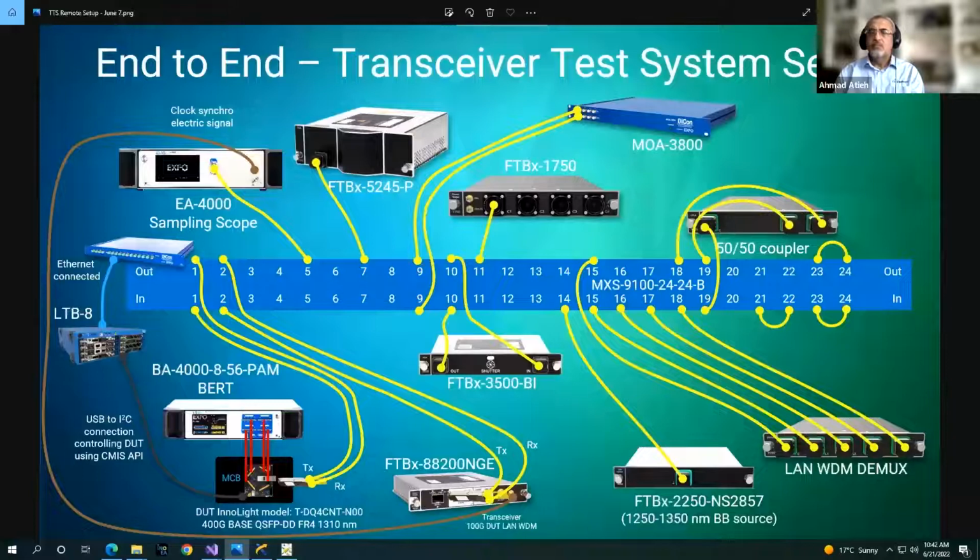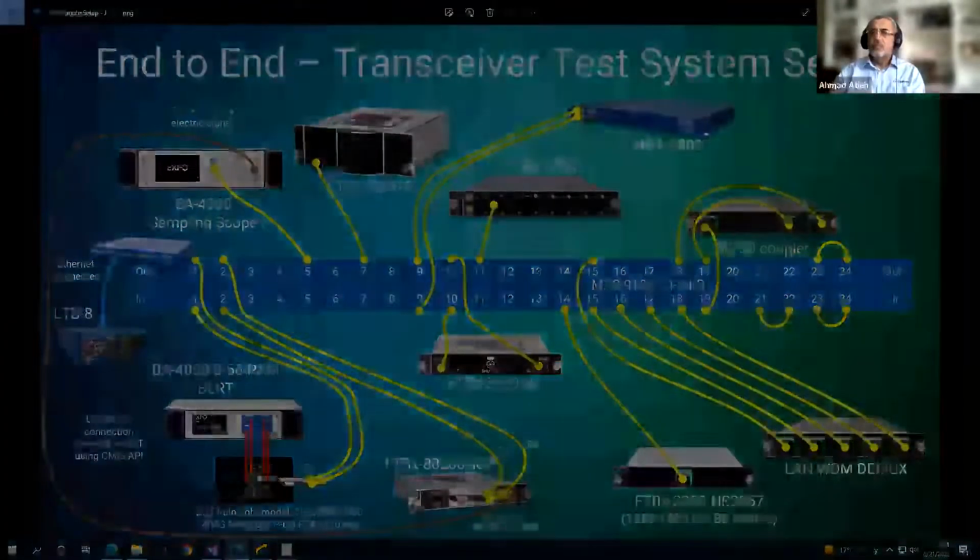As you just saw, the only thing that changed for each measurement was the routing on the optical switch, incrementing from 15 all the way to 18. Therefore, I have two options if I want to do this calculation. One, I could create a for loop that increments the routing after each measurement, or I can run a script using the APIs to change the XML file which calculates each channel separately, which is what I'm going to do in this example.